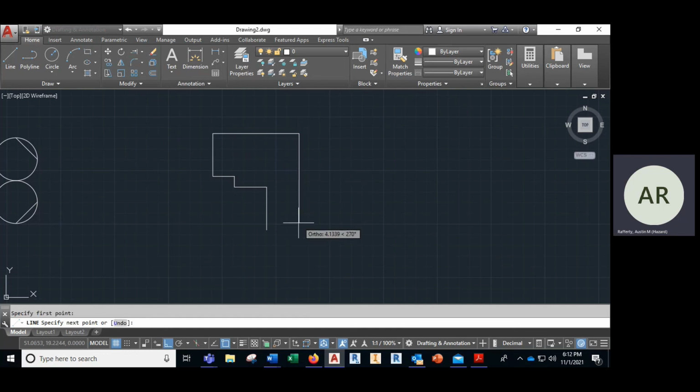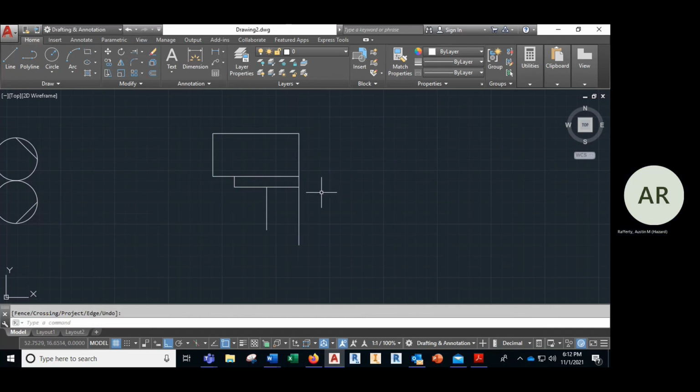Well, I'm going to add this line here. I'm just going to add a line that comes through here, because these lines should actually extend over to this point here. So I'm going to go back to the extend tool. I'm going to pick extend, and I'm going to select the object's boundary line. So it's going to be this line over here. This is where I want to extend to. Hit enter, and now I'm going to extend these 2 lines right here and hit enter. So there is my object, and I'm going to delete this because I don't actually need that.